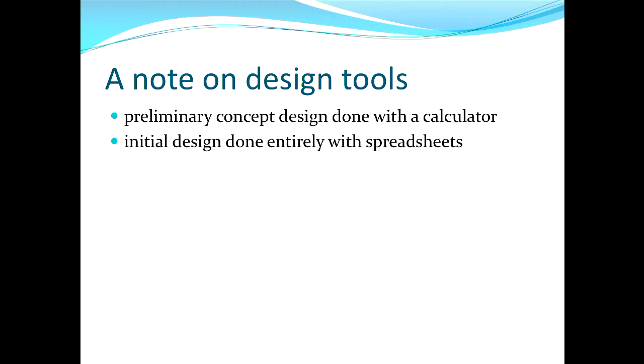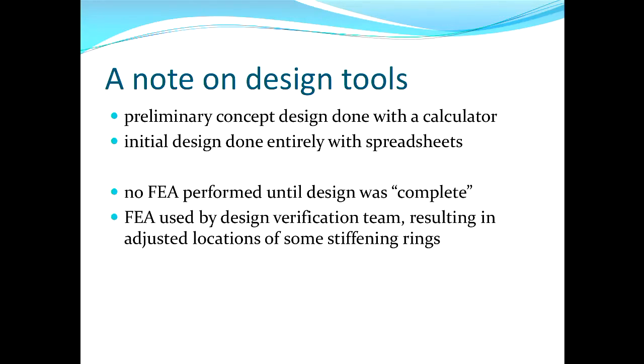You might think that other more sophisticated tools would be needed in a situation like this. It turns out not. Although FEA, finite element analysis, was performed, really at the end when the whole thing had been designed, all the thicknesses had been assigned, the design was essentially complete. Finite element analysis was used as a check, and helpfully, because some of these stiffening rings were relocated, or I think an increased number of stiffening rings was included to improve the factors of safety as was necessary.